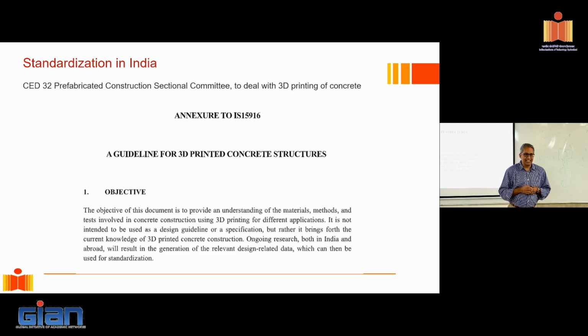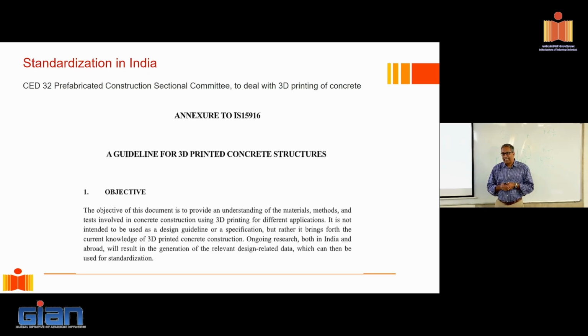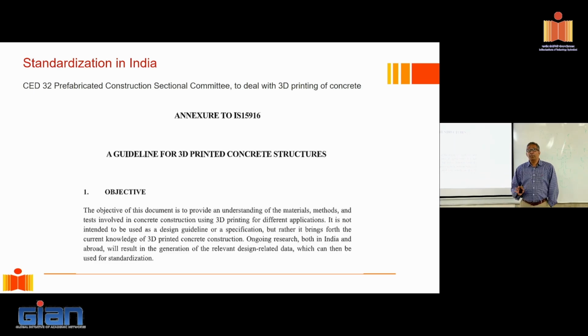How many of you would be willing to do that? Well, the reason is because it's called design by test. And all but a few very large companies like, say, L&T would be able to do such an exercise. So while data is still incoming, while we are still assimilating all the data from all over the world, I think they're not stopping you from building structures with 3D printing. They're saying, well, use your common sense, okay? And at the end of the day, you justify that you have adequate capacity, or you build something that's a prototype, load test it to failure, and use that as feedback for your design process. That's also allowed. Okay.